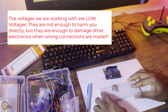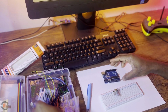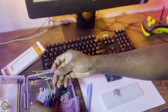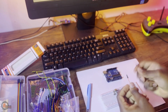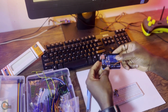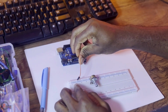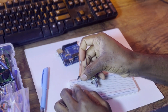Okay, I have my potentiometer in place and then my Arduino board here too. Since we are just using the Arduino board as a power supply, I need two simple jumper wires to take 5 volts from my Arduino board and introduce it to the positive part of my breadboard, and then also ground from the Arduino board to the ground of the breadboard as well.